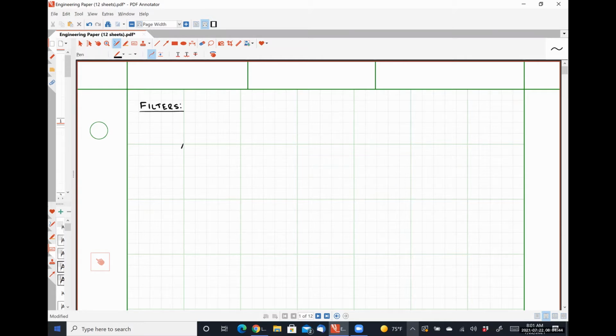And I'm going to describe them graphically at first. And we'll talk about the ideal filter response. And then we'll talk about the practical or real filter response. So let's say this first one is going to be a function of omega. They're actually all going to be functions of omega. And I'm going to look specifically at the magnitude of the transfer function, where the transfer function H of omega will be something that we discuss in a little bit.